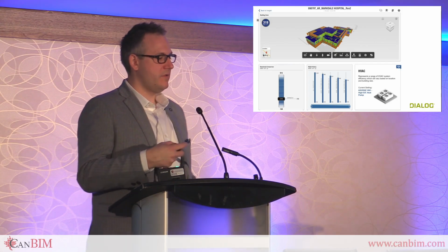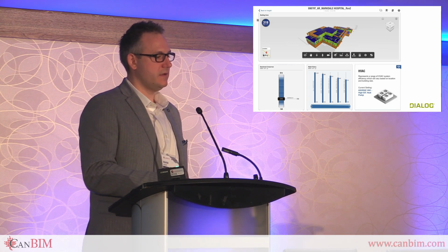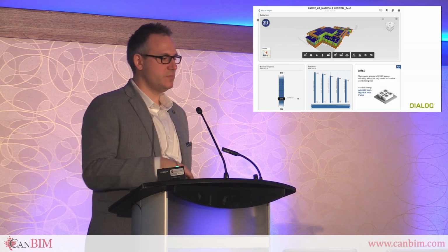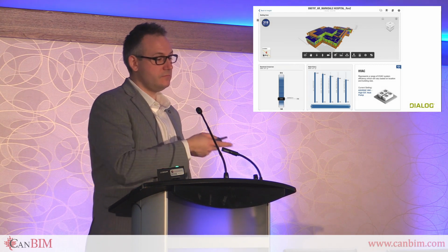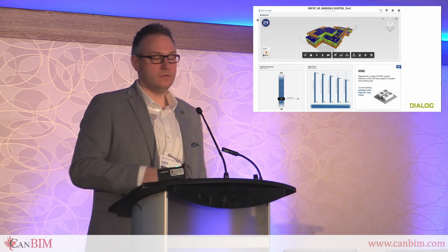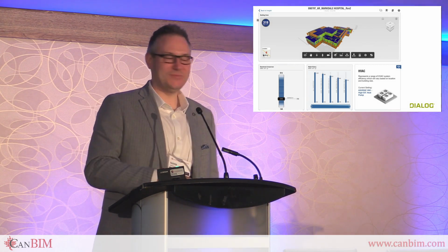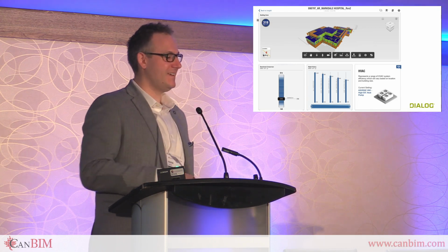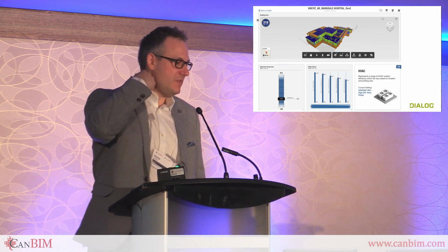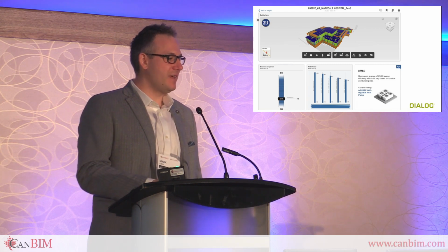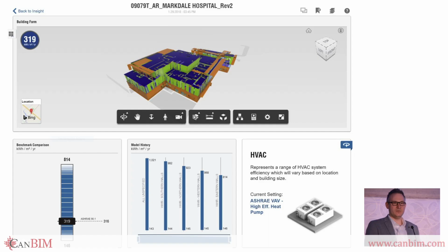So stepping back into building energy modeling for a second here, I had mentioned trying to achieve 2030 on hospitals. So Aslan will be familiar with this screenshot, which is Autodesk Insight. We are trying to evaluate right now, if you look at the EUI number returned in the top left corner, it's actually pretty spot on for a conventional type hospital at 320.